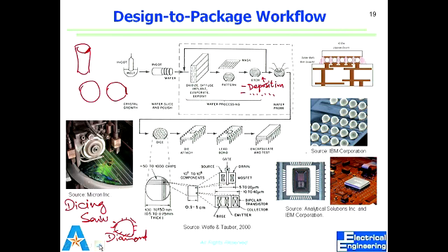So what happens in that red circle? You get that wafer. So this shows molten silicon, and we'll look at how it is done. Molten silicon, and this is what we call a seed. This thin thing is called a seed. So I have this fine, thin, pen-like structure, which is single crystalline material. And I dip it into a molten crucible. Crucible is a dish, just to withstand high temperature. It's filled with molten pure silicon. I dip it and I draw it back.